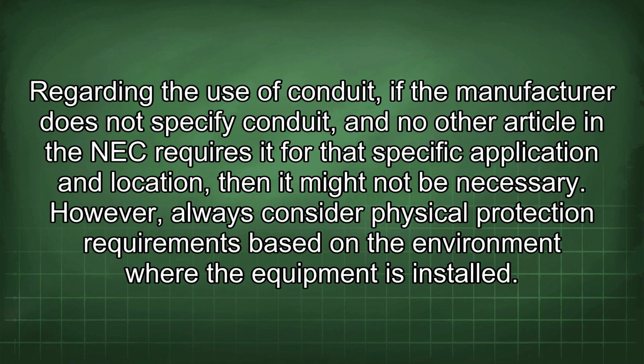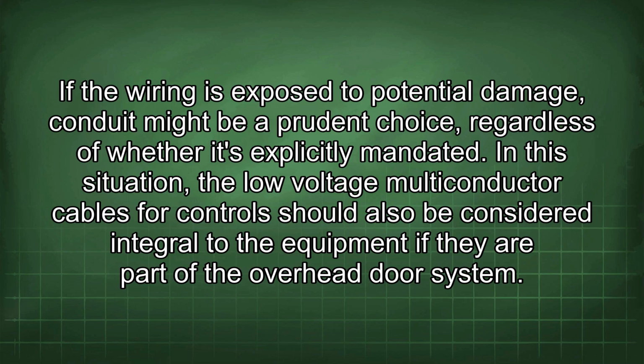Regarding the use of conduit, if the manufacturer does not specify conduit and no other article in the NEC requires it for that specific application and location, then it might not be necessary. However, always consider physical protection requirements based on the environment where the equipment is installed. If the wiring is exposed to potential damage, conduit might be a prudent choice, regardless of whether it's explicitly mandated.